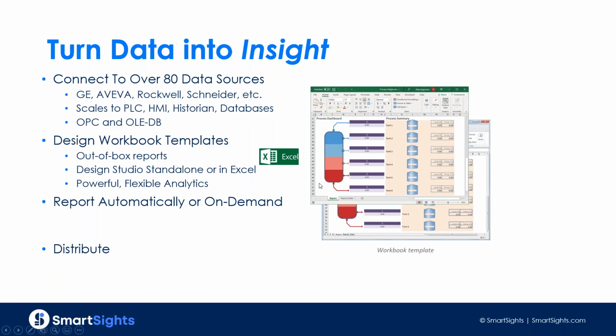Once you've designed a template, you can map data onto it, and the system has a powerful analytical calculation engine. So we can look at the raw data being produced in a historian and turn it into metrics, uptime, downtime, min, max, average, totals, deltas, all kinds of different options in terms of producing calculations, slicing them by time, applying filters to them. And so this is really within an area of power of the product in that we're not just, again, feeding you the fire hose of data coming out of the historian, we're turning it into actual information and returning that in the report.